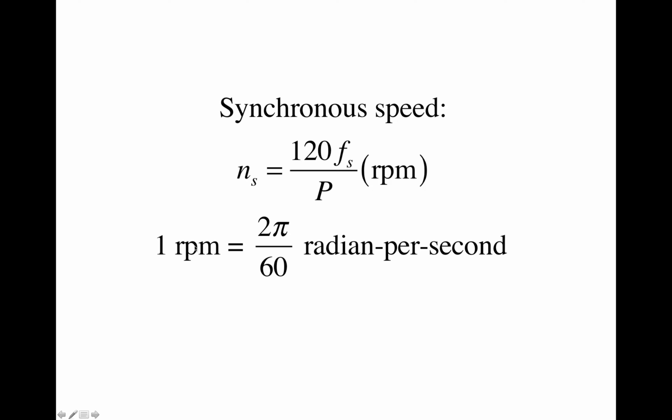In the previous video, we talked about how the rotating magnetic field is set up inside the stator. This magnetic field is not created from a permanent magnet. It's created from electric current based on Ampere's law. And the rotation of the magnetic field is due to the temporal variations of the amplitudes of the three-phase alternating current, which is readily available from our electric power system.